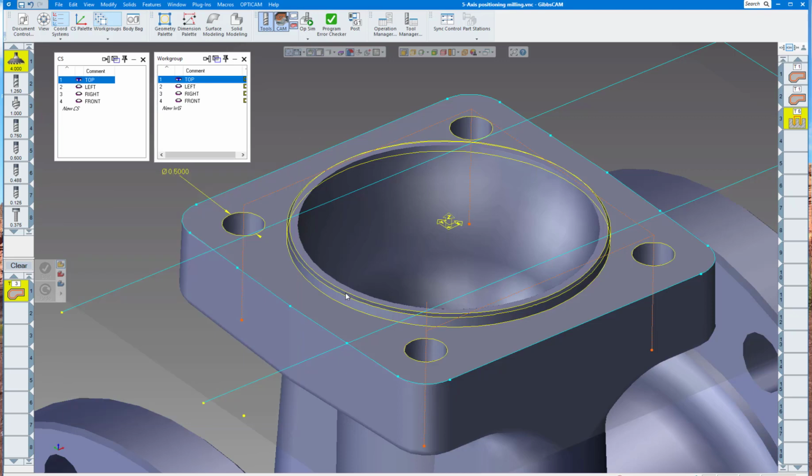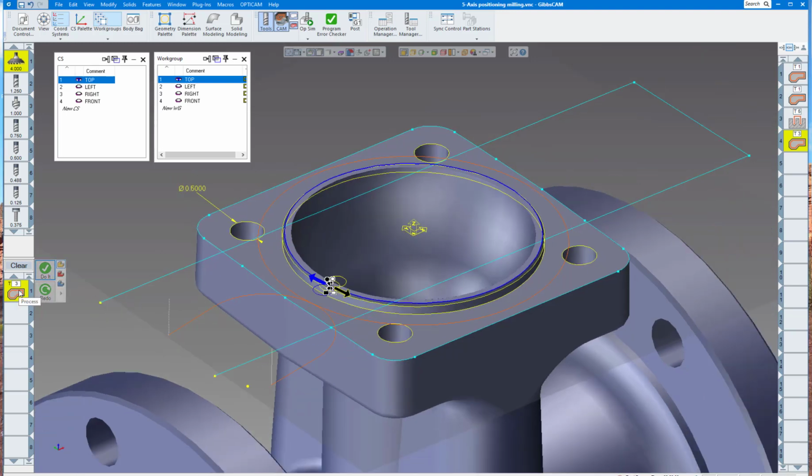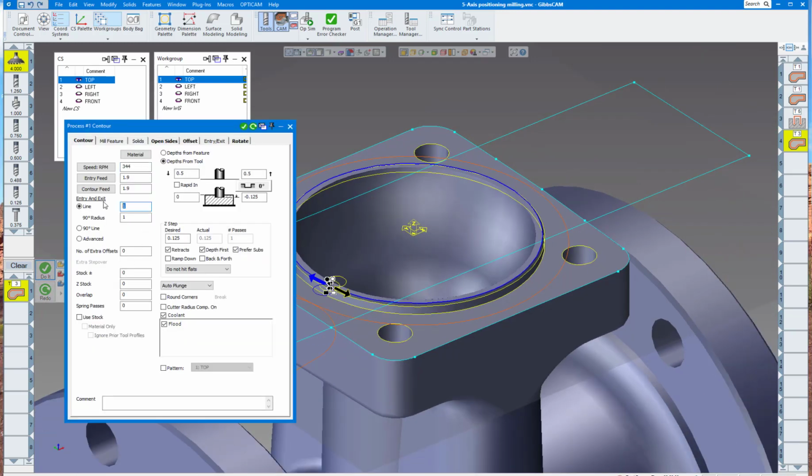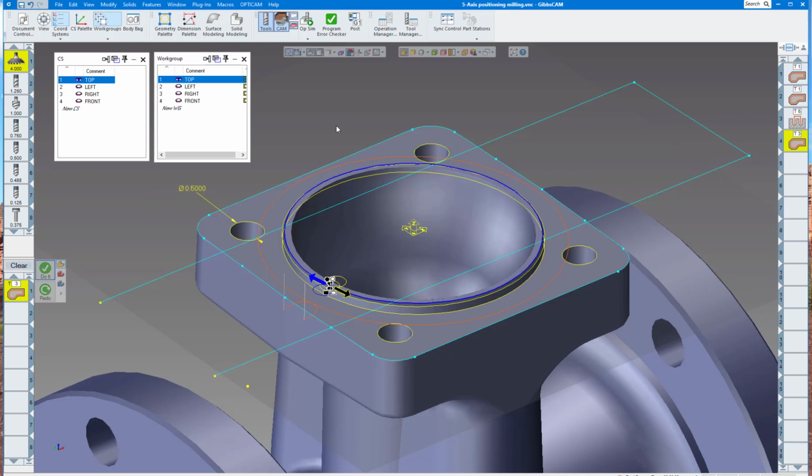And if I select this edge right here, I can go around there and do a chamfer. Probably really don't need that large of an arc in, arc off. So we're going to go to 0.2. And that looks a little better there.